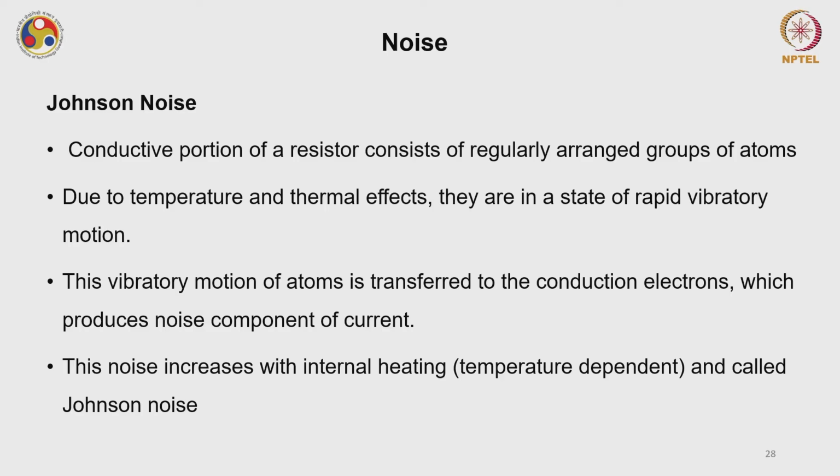Okay, this vibratory motion of atoms is transferred to the conduction electrons, which produces a noise component of current. This noise increases with internal heating, that is, it is temperature dependent, and this noise is called Johnson noise. I have mentioned that due to temperature and thermal effects, the atoms of the resistor are getting disturbed or have some vibratory motion.